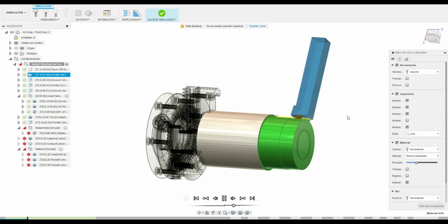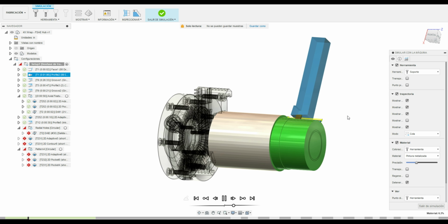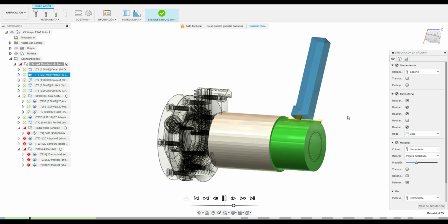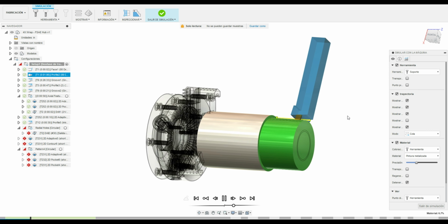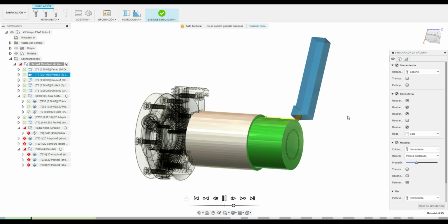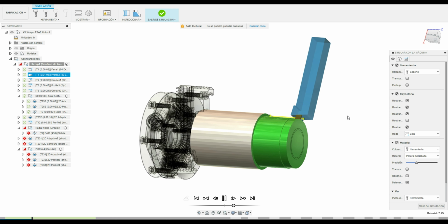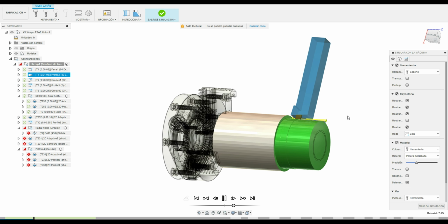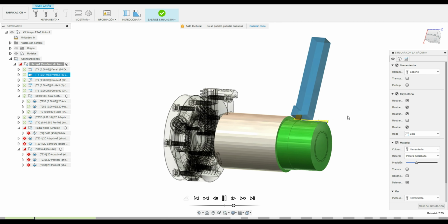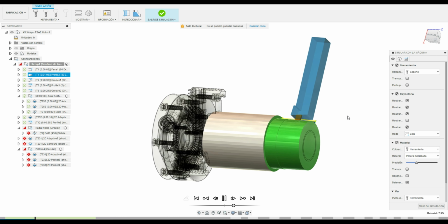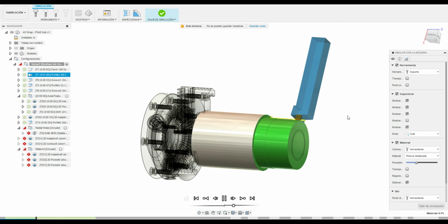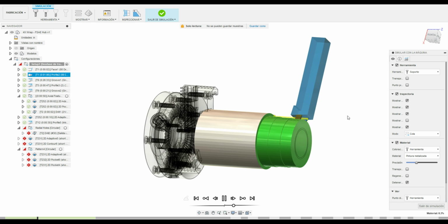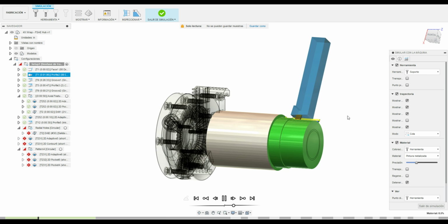We begin by defining the setup configuration, the foundation of every machining project. Here, the stock material is positioned in reference to the work coordinate system. We carefully define the origin point, tool orientation, and machine zero to ensure maximum accuracy. This alignment guarantees that what happens in the digital environment will be perfectly replicated on the CNC machine. Precision at this stage eliminates costly errors downstream.